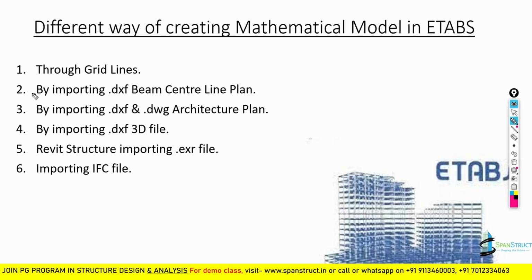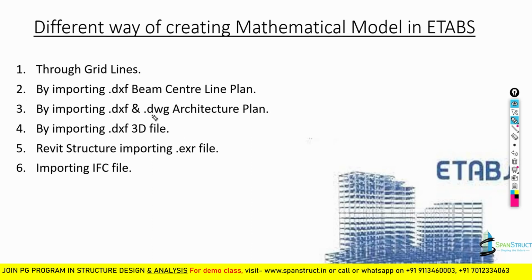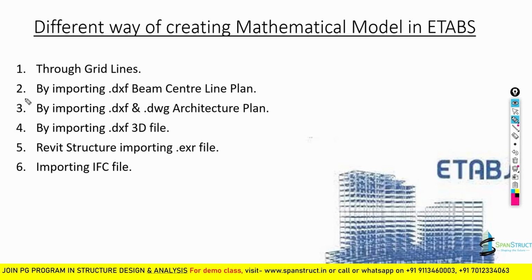We have come to the end of this lecture, where we have seen different ways of creating the mathematical model in Etabs. We have discussed a lot of methods through which we can create a model in Etabs. Now a very important question might be arising in your mind: which method is the most commonly used and easiest method? The most commonly used methods are through grid lines and by importing a .dxf beam center line plan. These two are the most common methods for creating an analytical model in Etabs.